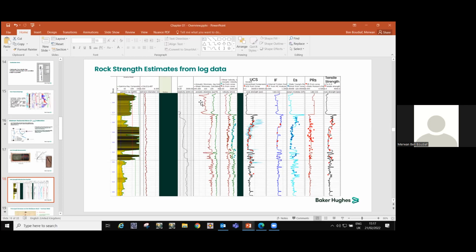For the cased hole, this term is used in cement evaluation. When you are interpreting your VDL or CBL, the presence of fast formations needs to be known before you start interpreting, because, for example, if you have anhydrite... We'll not go into too much detail. For people who have experience seeing a VDL, you have your casing arrivals first, and then the formation arrivals.